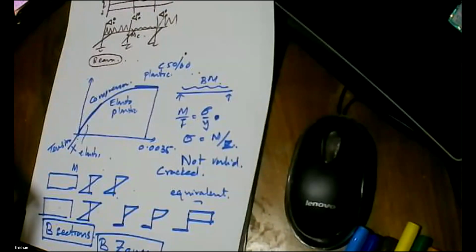There's a big problem in that particular site: the rock has cracked vertically. Because of that, the unconfined compressive strength is very low, and the geotechnical engineer cannot give a high end bearing.